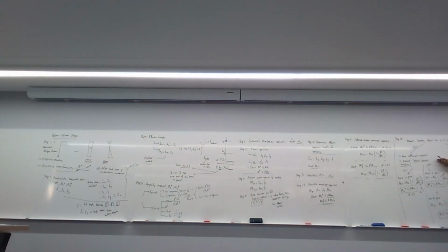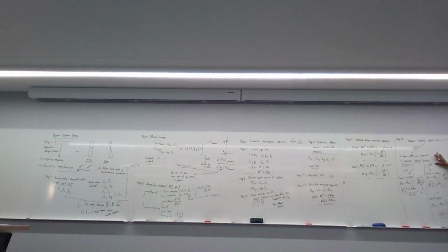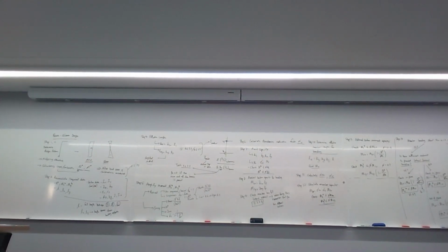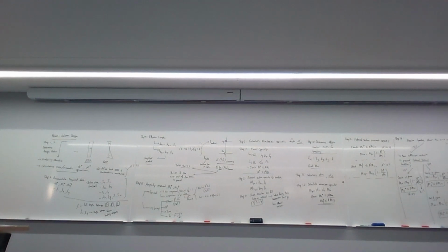If there isn't any sufficient restraint to prevent lateral torsional buckling, which means you don't have continuous lateral restraints, it's going to buckle, then you use this. You have to check both in-plane bending and out-of-plane bending. Just remember, same thing, NCX here, NCY here, both are KE equals 1. You have to recalculate them. It's quite sneaky, but that's the check that you have to perform.